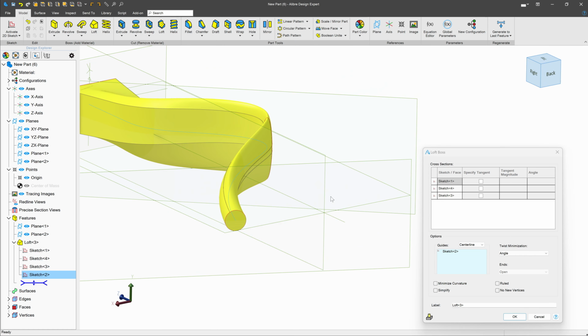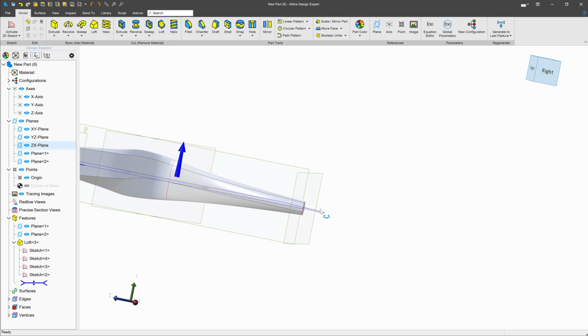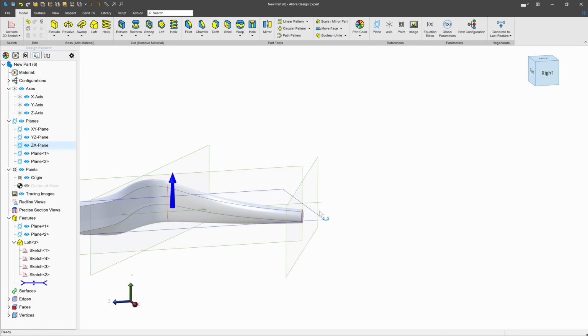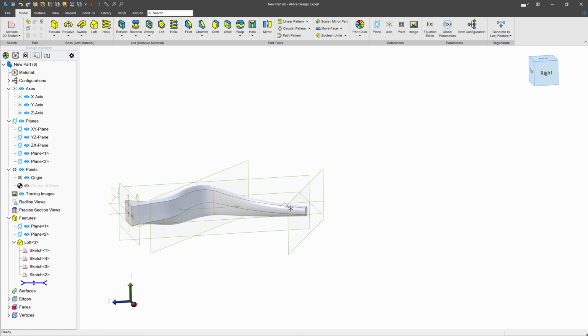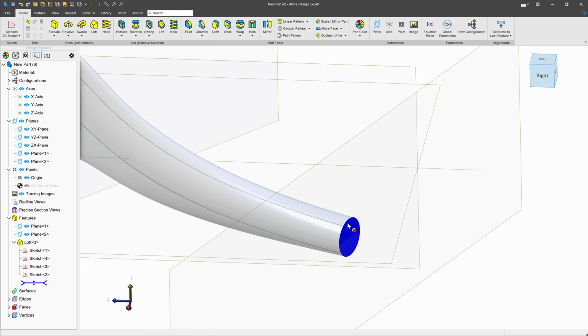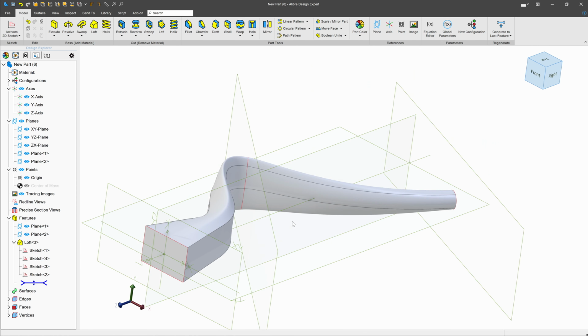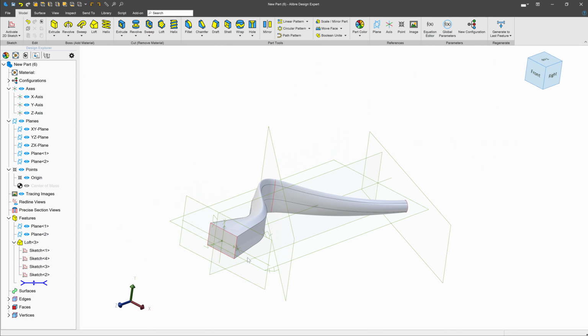So sometimes, if you're in a hurry, you can get away with doing a loft like this that is very eccentric. But if you run into any problems, remember, you need to have the control of making this into 4 elements so you know where these corners should line up on your next profile, and then making this, of course, into 4 arcs. But we seem to be able to get away with this the way that it is. So I'll save this as our weird loft.